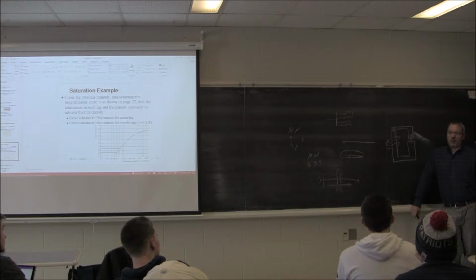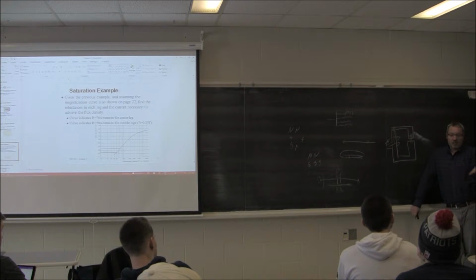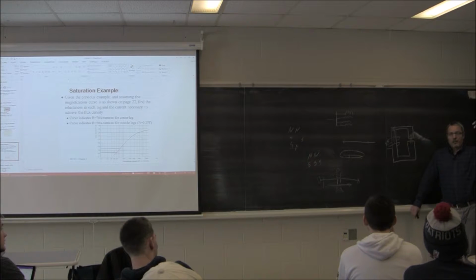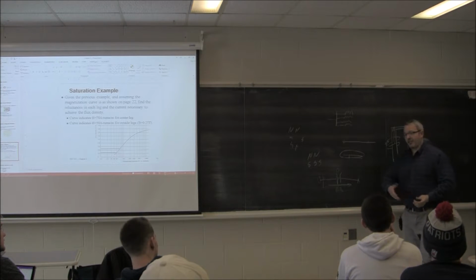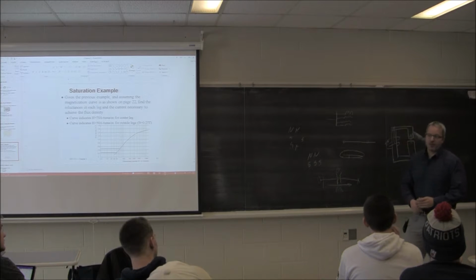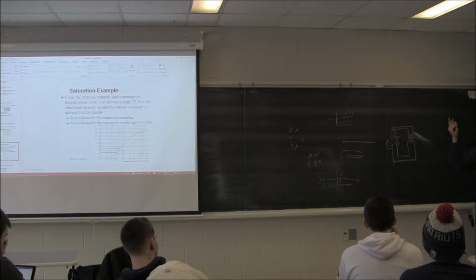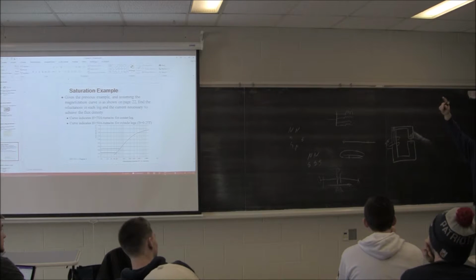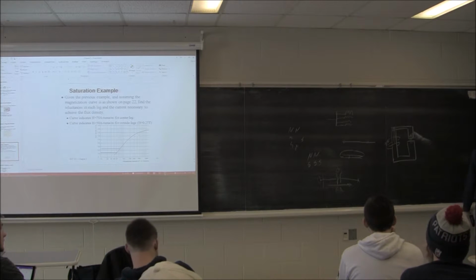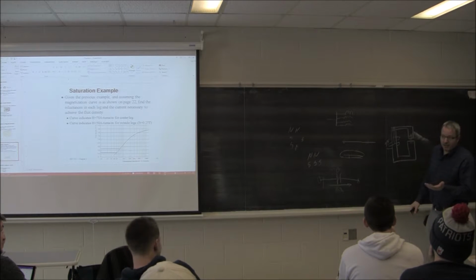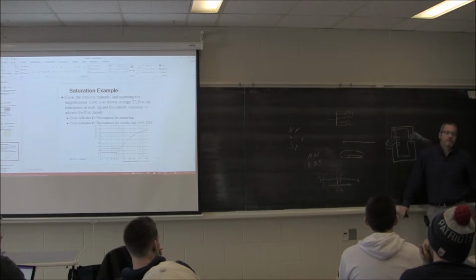Because inside there are 3 pole-mounted transformers, not mounted on a pole, mounted basically on, like, desks essentially. So you have 3-phase 4160 coming in, steps it down to I think it's 208. So you could walk right up if it's energized and you could access the live 4160. You just walk right up to it. It's open air? They're pole-mounted transformers. They're designed to be up 35 feet in the air. So what you see on the top of a pole, that's walking distance. So that's perfectly available to you if you had the key.